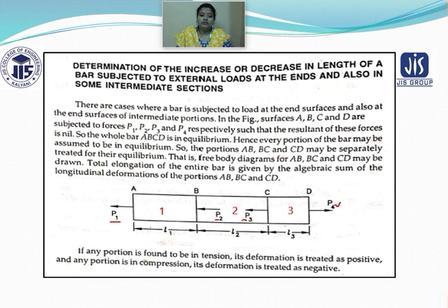Now you have to consider one thing: if a portion is found to be in tension, then the deformation is always treated as positive. But in any portion where the load is compressive, the deformation has to be treated as negative. So this is the basic consideration you have to keep in your mind.